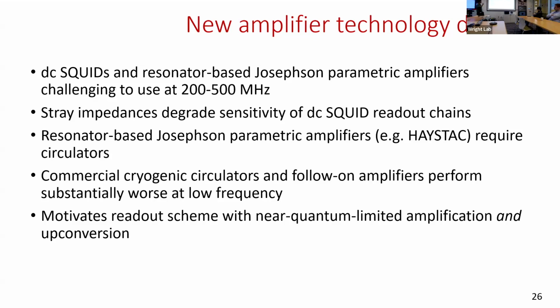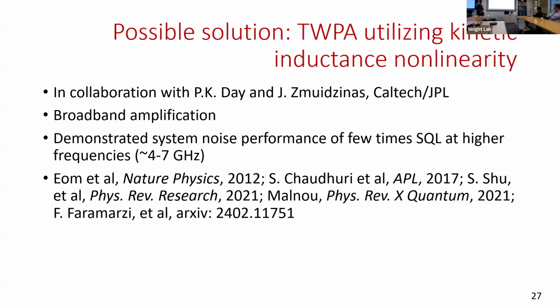using schemes where not only do you have near quantum limited amplification, like you would get with a JPA or a DC SQUID, but where you also have up conversion so that you can move away from this frequency range where the follow-on microwave components may not behave so well. So this gets us to our possible solution.